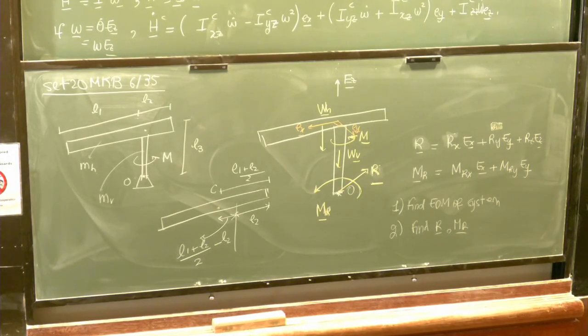The only part that contributes should be the x distance and then the z distance here, so it should be minus L2 over 2 times the height L3. So that's ax. Right, exactly. So Ixz is not 0. Iyz is L3 times z. Iyz would just be 0 for this one because it's symmetrical. The whole thing is symmetrical, so it should just be 0 for yz. Use the formula.